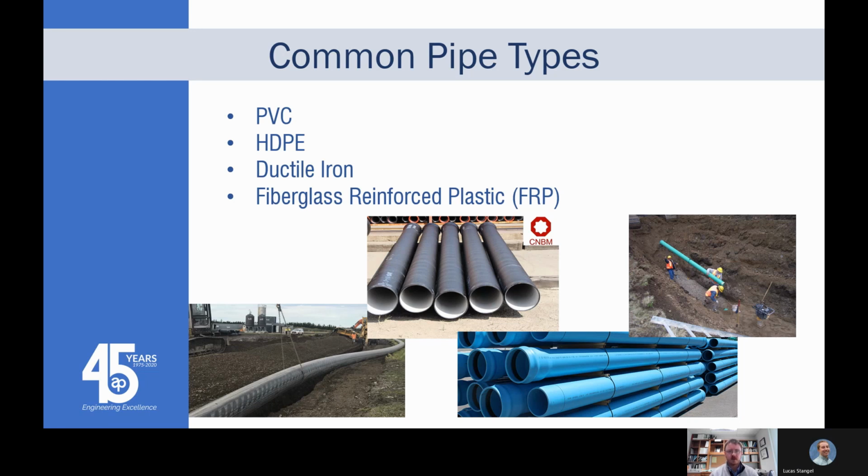It's not as common, especially not in our region. We've had some contractors that have proposed to use it on projects as a substitute for C900. It's the same material, same resin, it's just how it's constructed is a little different. So my understanding is, like a C900 pipe, if you've got an 8-inch pipe, they mold it and there's a certain thickness. The C909, or the molecularly oriented PVC, they essentially take that same 8-inch pipe and they